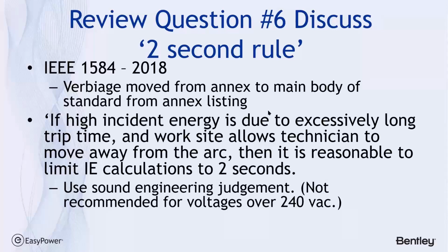And then Tori is saying, what is the maximum time you apply for locations above 240? Again, there's no guidelines for this. I personally am, again, if we have a protective device that's not tripping within 2 seconds, there's more than likely something wrong with the coordination upstream of that bus.